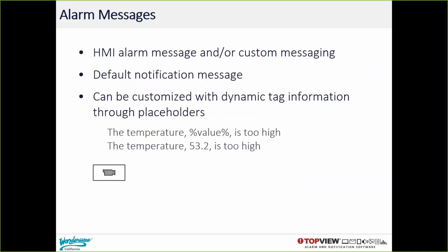The alarm message in TopView is the default notification message. When you use SCADA Connect to sync your Wonderware alarms with TopView, the alarm message is initially set to the alarm description or comment. But you can edit the alarm message to add dynamic information through the use of TopView placeholders. A common use of this feature is to embed the analog value that triggered an alarm into the actual alarm message. So let's take a look at an example of that.